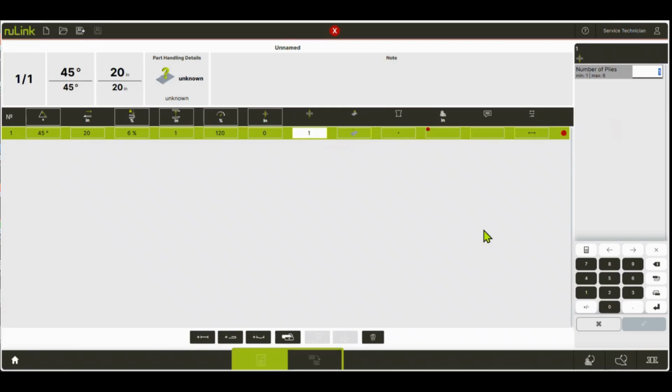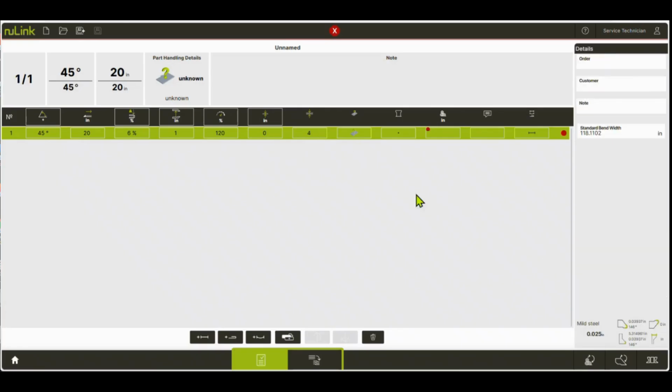So you have to come here and say, hey, machine, yes, I'm running 4 of these, right? And it'll say, oh, okay. And then it'll set that alarm to if it gets thicker than 4 of those parts, right? But keep in mind, if you're using a number anything other than 1, you need to be mindful, just like you do in that nice fancy draw programming. And each time you alter this parameter, you need to make sure that you're operating within the capacity of the machine and you have the proper tool on for that, okay?